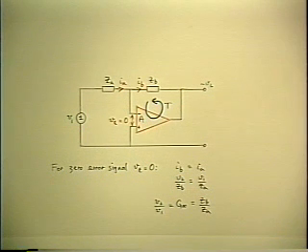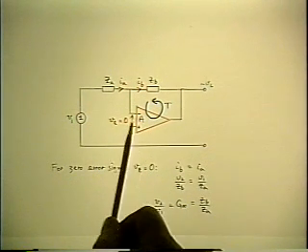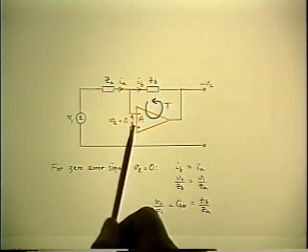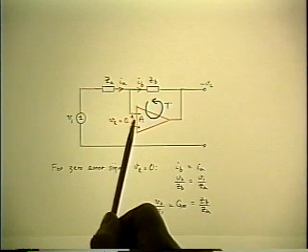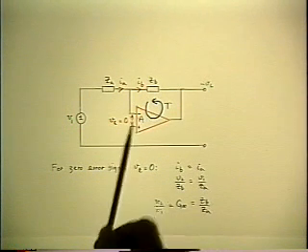If you've got 0 voltage, you're going to get 0 current, even if the impedance is only 1 ohm. So it's important to notice that no restriction is implied in this result to do with whether the input impedance is high or not.